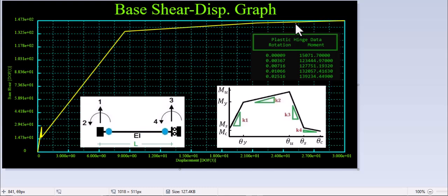You see, guys, in the first example we have one beam element with 4 degrees of freedom, and we're going to define the plastic hinge at the beginning and end of this beam element, and then run the pushover analysis as an incremental displacement. So in degree of freedom 3, we're going to have an incremental displacement, and